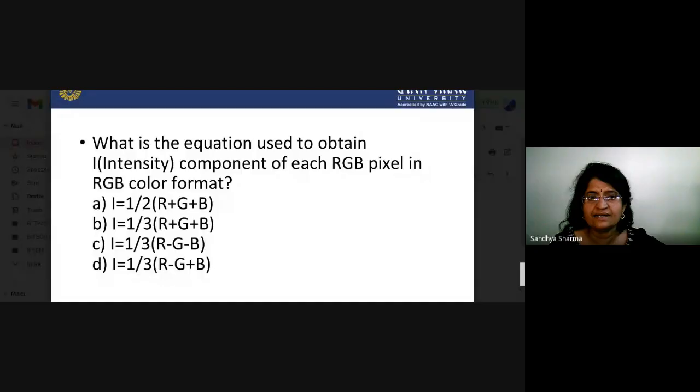There is compatibility: a black and white signal will easily be shown on the screen, because our screen is made of different pixels. When working with color signals, each pixel is divided into RGB, red, green, and blue, and they illuminate accordingly. The signal can be converted into the brightness part, and according to its brightness, our screen will be compatible with the black and white signal.